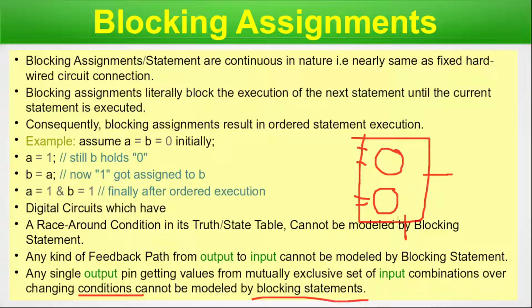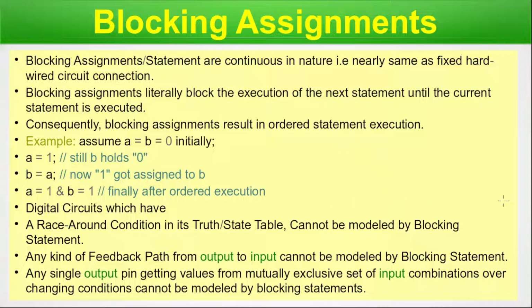The first one, if you change its value 0 or 1, the first two input combination will be connected through this, and these two, if you change it to 1, these two will be connected. So you can realize this is a kind of muxing operation, right? However, in words we have generalized it, and it is not limited to the mux. If there is some mutually exclusive set of input combinations in any digital circuit, in any complex design you come up with which is much more complex than a mux, it cannot be modeled by the blocking statement,